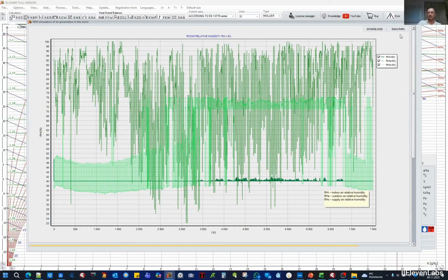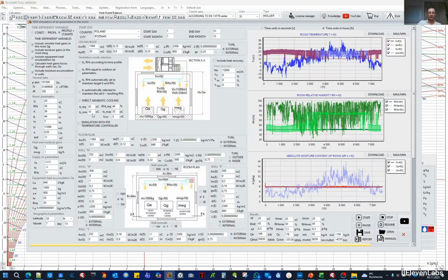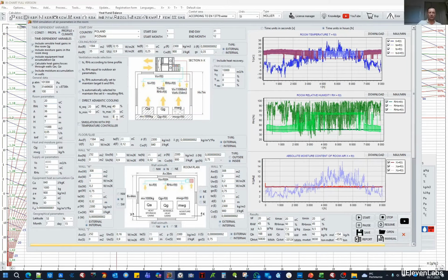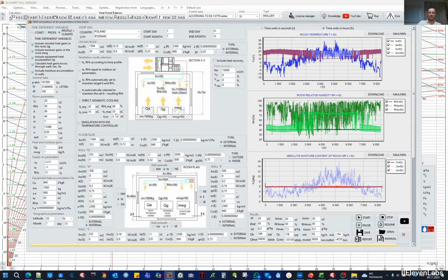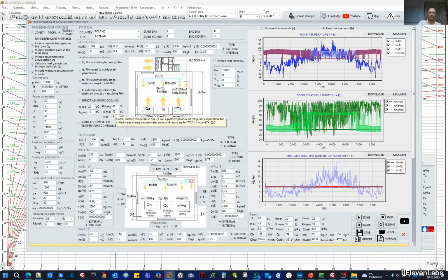And in this case, we have two options. Either we lower the supply air temperature, or we lower the temperature of the cooler wall. Of course, here we are also limited by certain parameters, because we cannot go below, I think even below plus 3 degrees, because then there might be a risk that the cooler will freeze and frost locally, which is not a good idea. In connection with the above, we can determine a critical point where we must obligatorily switch to an adsorption drying system under certain parameters.